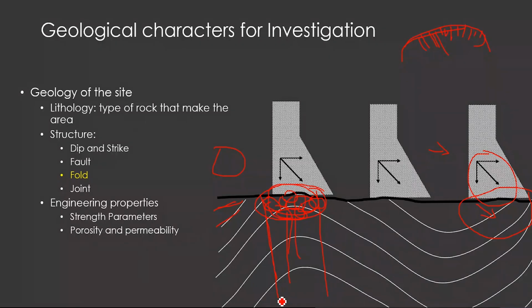So that is not a very good foundation rock we can consider for the construction of a structure like a dam. This area is highly disturbed, and the rocks may not have a sufficient amount of strength to hold the weight of the dam and the reservoir. So this condition can be taken up as a safer condition, and this can be considered as the worst condition.